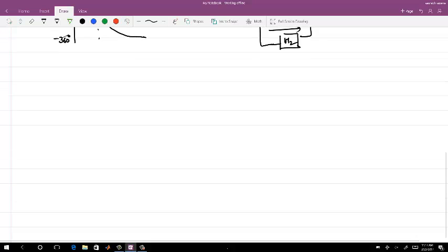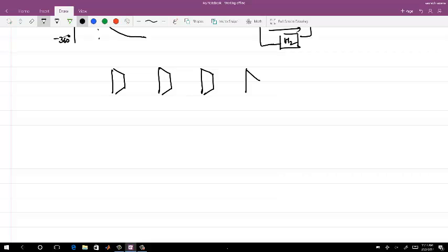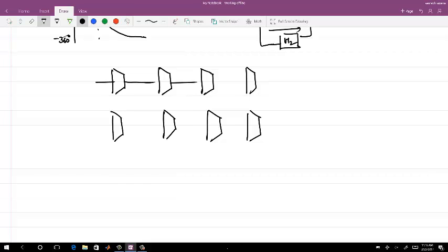Let me then ask one question here. Earlier you saw that I was using 2, and it was a little bit difficult to make it oscillate without having cross coupled inverters as such. So let me say I increase the number of the same cells to 4. And now the same cross coupling I will have.